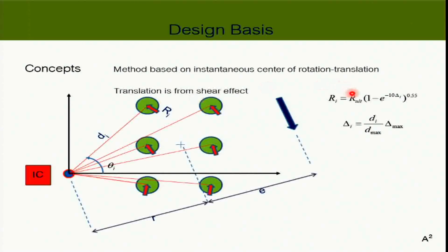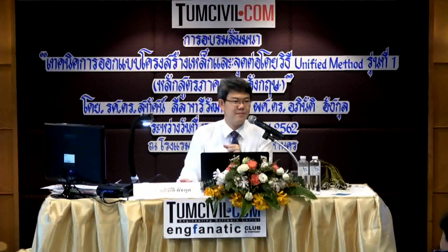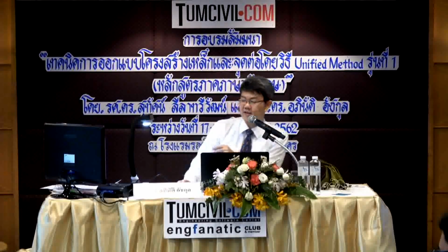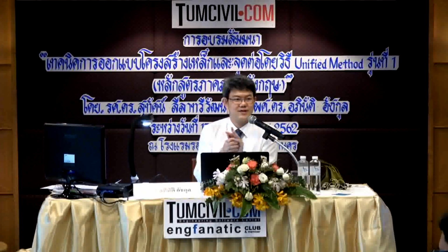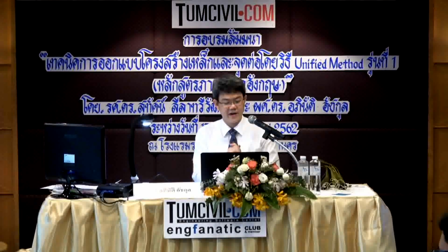Sounds scary, right? Because we need to keep using trial and error until we know where it is. If this is the correct point, the calculation from the load-deformation relationship will lead us to perfect equilibrium. So imagine if you assume the location wrong, you will have a wrong deformation and therefore the wrong force, and you will never have equilibrium. That is why it took me like a day to do it. Anyway, somebody has done this for us. All the results of this approach are presented in the design manual, which some of us have, some of us may not have. If you have the manual, you can just look it up in the table and take the force out of that table, and all the calculation in the table is based on this approach. But if you don't have that, we're just going to have to stick with the classic. That's it for the bolts, I suppose.